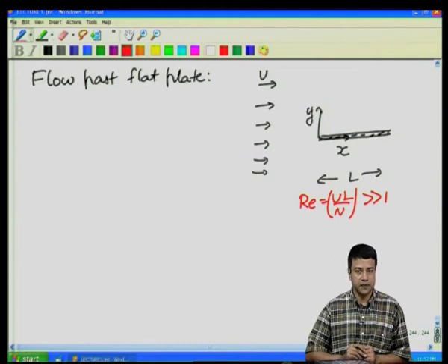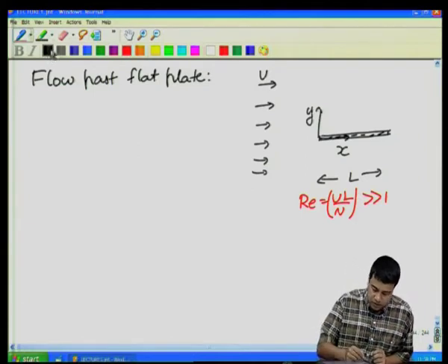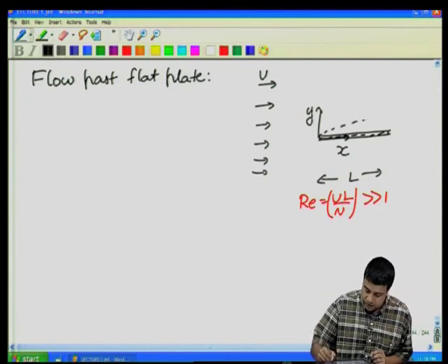Okay. If we assume Reynolds number is large and just neglect the viscous terms, we simplify the equations from a second order differential equation to a first order differential equation, and then we are not able to satisfy the tangential velocity boundary condition at the surface. In order to satisfy the tangential velocity boundary condition, we postulate the existence of a thin layer of thickness delta at the surface.